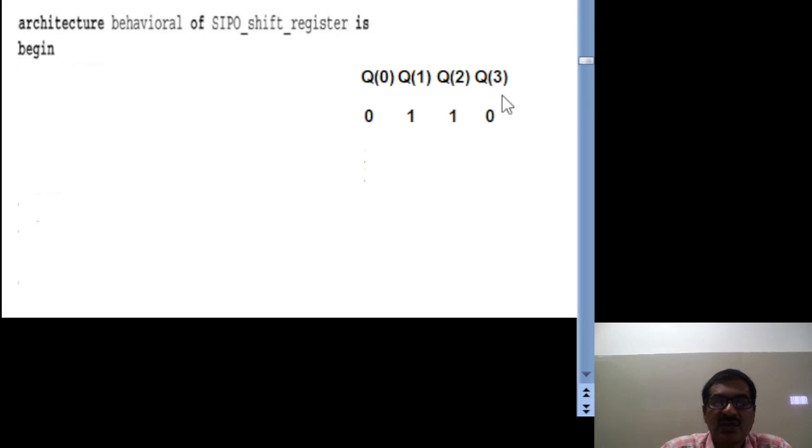Okay, since it shows the right shifting operation, and that too one bit, it shifts towards the right hand side direction for each clock pulse. That is, after applying the clock signal, the data of the shift register moves one bit in the right hand side direction and the MSB position is occupied with the X. Okay, so that is represented like this.